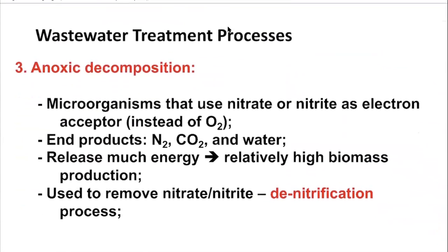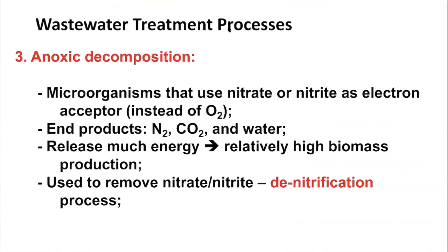So there are also two more. One another is the anoxic decomposition. If you look at this NO here, if it involves anoxic, it generally refers to the nitrogenous species, which is reducing the nitrogen, because we know that nitrogen is a nutrient, right? So if the wastewater contains a lot of nitrogen, and then if we don't deal with it, then it's going to cause the algae bloom and cause some other environmental hazards. So for the wastewater that has a very high concentration of nitrogen, we have to go through this anoxic decomposition.